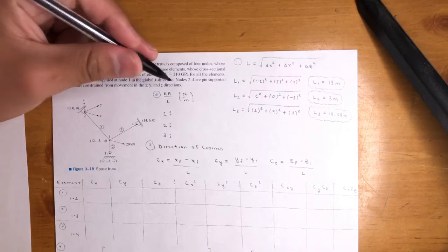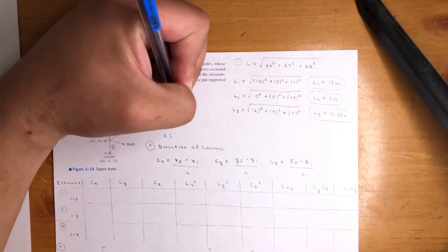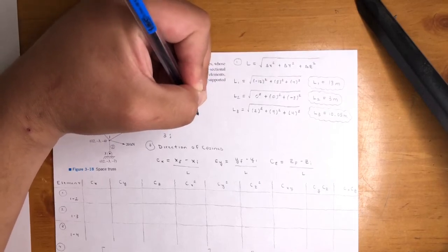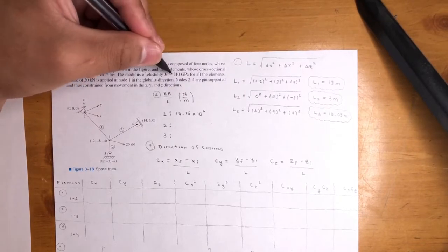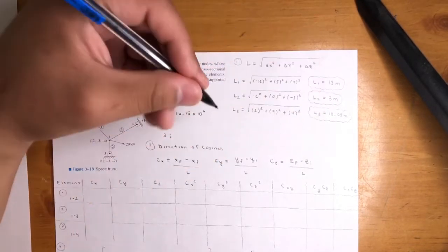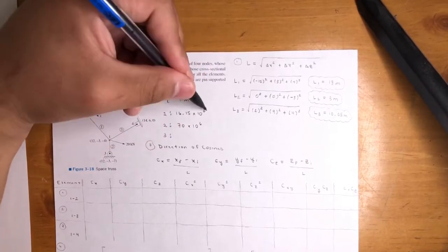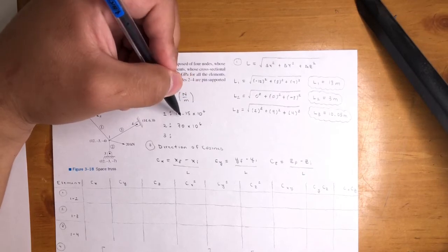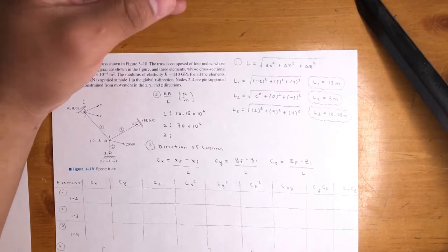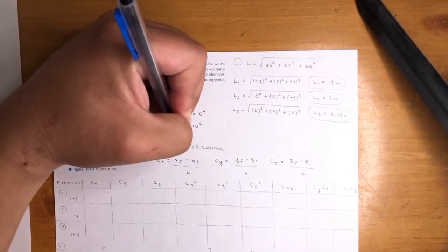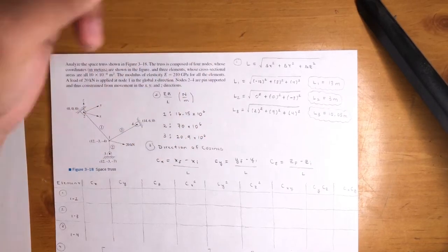So 2100 times 10 to the 5th divided by 13 in the first one, you will get 16.15 times 10 to the 6 Newton per meter. For the next one, same thing, right? 2100 times 10 to the 5th divided by 3, you will get 70 times 10 to the 6. I just moved it one decimal over, so I'm getting 10 to the 6. In this case, it would have been 161.5 times 10 to the 5th, but it's just decimals, right? And then finally for this one, we will get 20.9 times 10 to the 6.